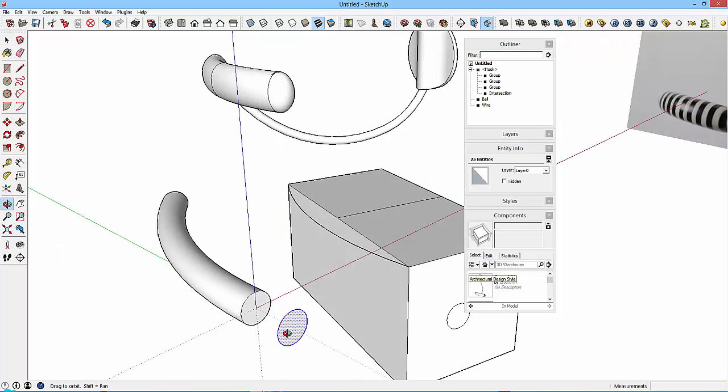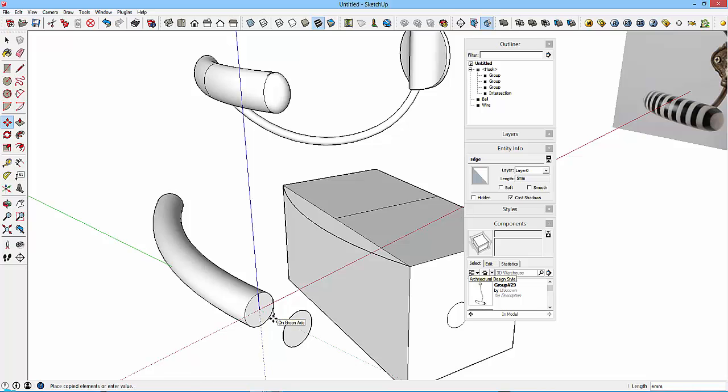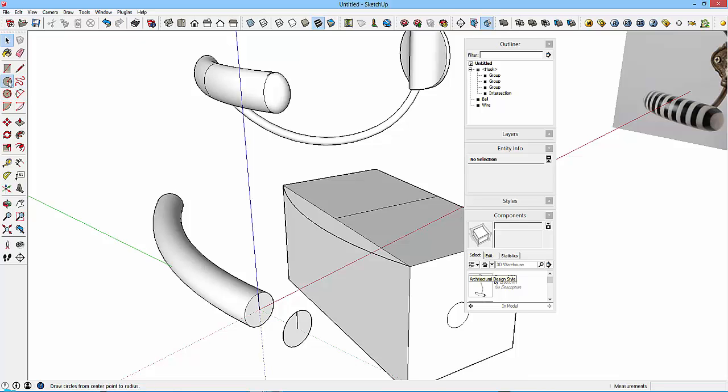15 mil. Now what I also want to do is take another circle, so that's going to be on the blue axis, and put it centrally on this. So I'm going to put, if I can find that midpoint, I'm not sure whether I will be able to, hover over that for a bit and track up. No, I'm not going to be able to do that. Move that down to there and then move that 15. That's going to give you the midpoint of that. And then I can put the circle, shift key, hover over that point, track up, click and drag.